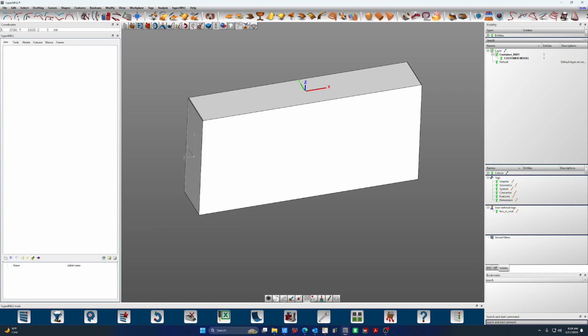Even if you've saved, sometimes, depending on your action, reverting to a save might not necessarily get you something back. If you've deleted a toolpath file or stock model and overwrote it, it might just not exist anymore. So undo, redo only works in the CAD workspace. Filtering, both these tools are basically selection tools for us.